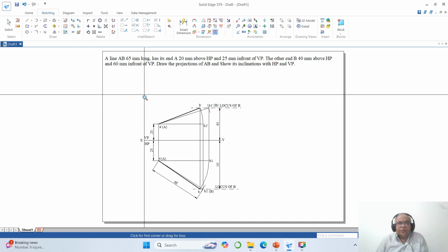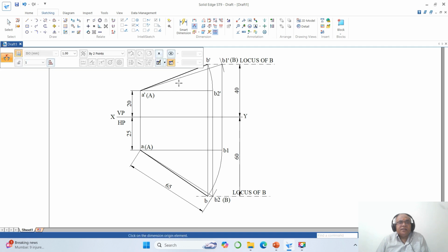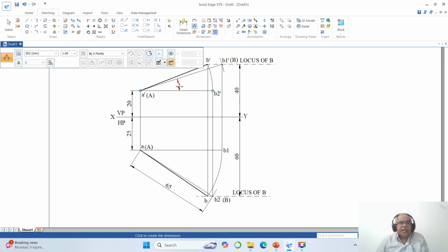Now you just go to zoom window. Then you go to angle between this line and this line. So what is the dimension? The dimension is up to the second decimal point we want. So clear the dimension text. So you just go to nominal, put on black. So now you have got the arrowheads. Similarly, right click, select between these two. So you're going to get alpha. Then similarly, between this and this, you're going to get beta. Sorry, this is 5. And then you right click and take these 2 dimensions.